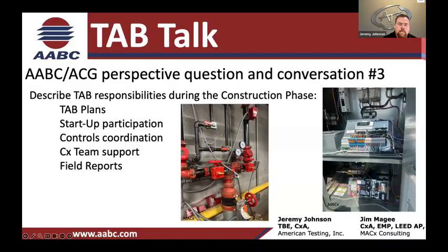I totally get that. And I think you can look at it too from a perspective of when you have independent systems, when you have independent chilled water system, control valves, auto flows, air terminal units, right? And they rely on pressure. They rely on pressure in the air duct systems and pressure in the water systems, differential pressure. And that's a gauge of potential, right?